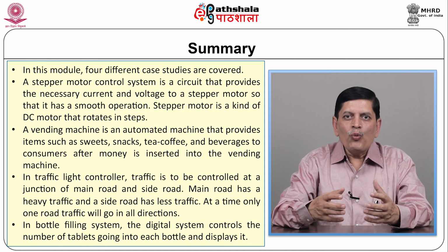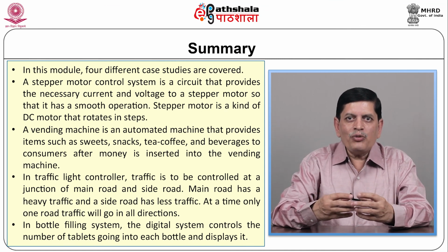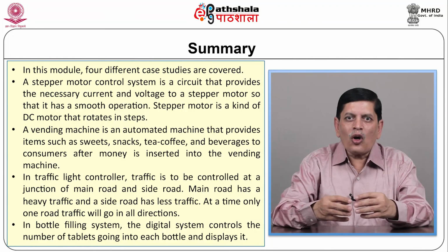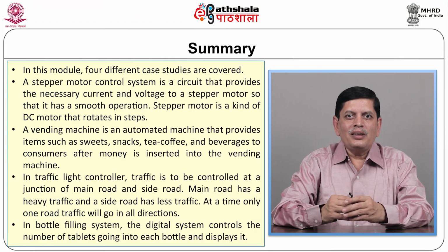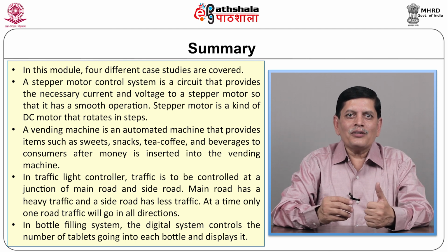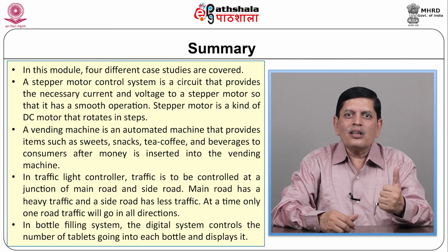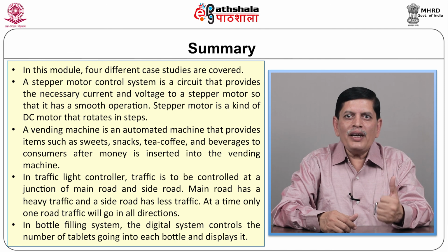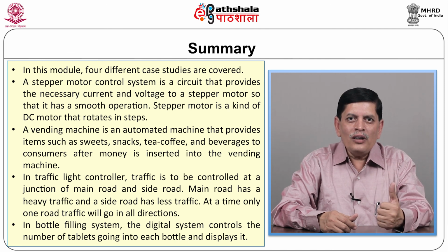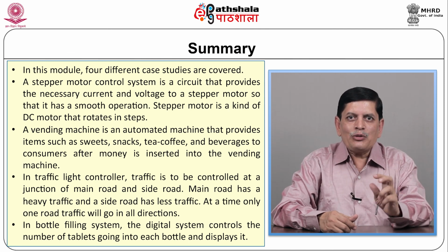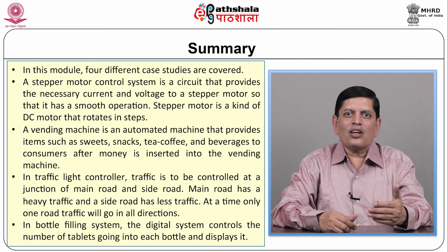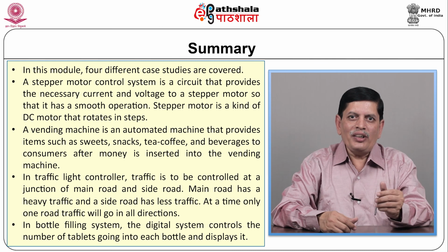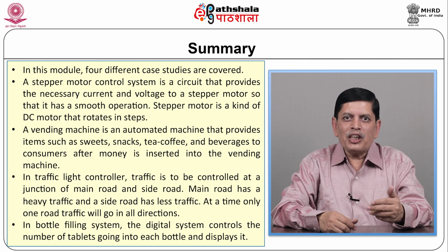In this module, we have applied the knowledge that we have gathered so far in almost all modules to several system design applications. The first system design application we have studied is a stepper motor controller system, where we have controlled the stepper motor angle as well as the speed at which the motor can be rotated. It depends upon the clock frequency and the angle through which it would be stepping.